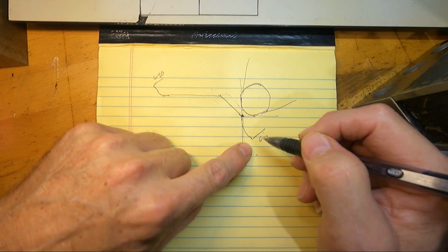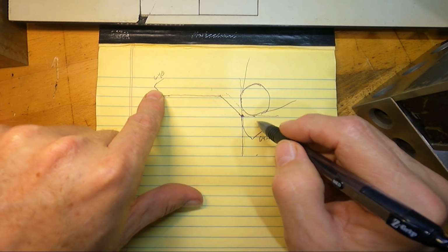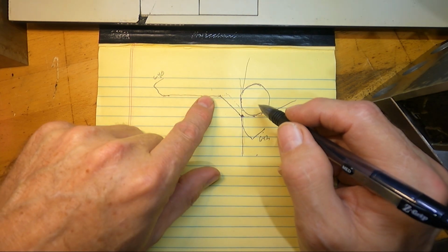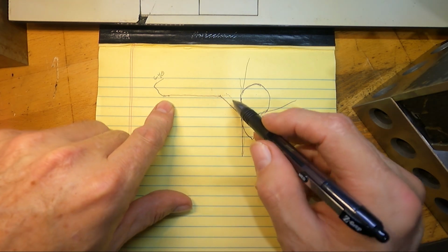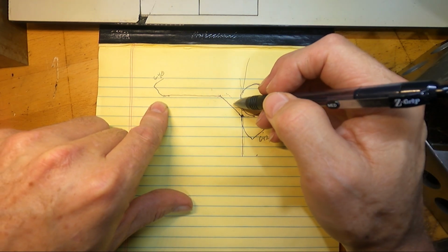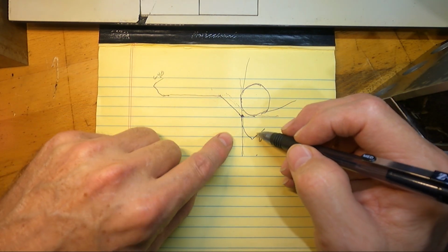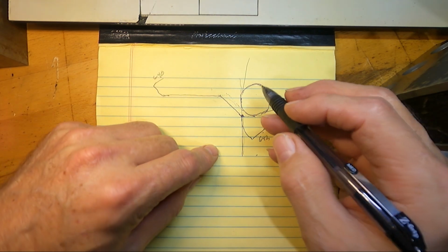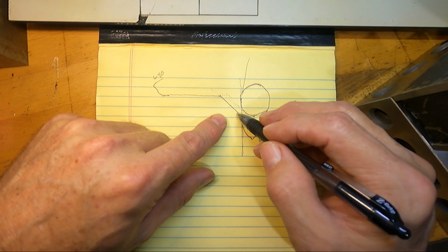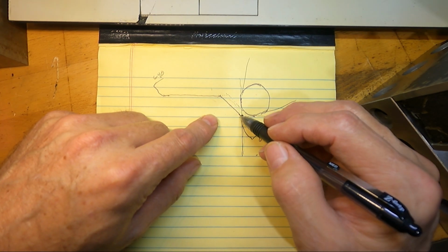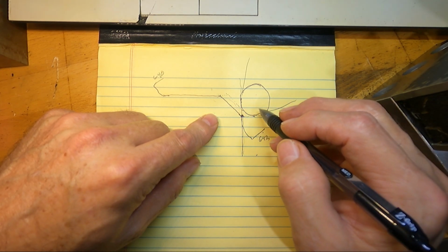So this would go around the contour, and you could program the actual shape of the part. So in the days before we used CAM software a lot, and we did this all manually, we could program the actual shape of the part and use tip comp to go around it for the finish cut. And for the roughing cycle, you could use some kind of a canned roughing cycle on the lathe, and you could just rough this, and it would leave stock on these chamfers and stuff, but it really didn't matter that much. You could just cut it with tip comp around here, and it would finish it to size. And if you had close tolerances on these chamfers or radiuses, if you had a radius anywhere, you could adjust that by adjusting the radius of your turning insert that you were finish cutting it with.